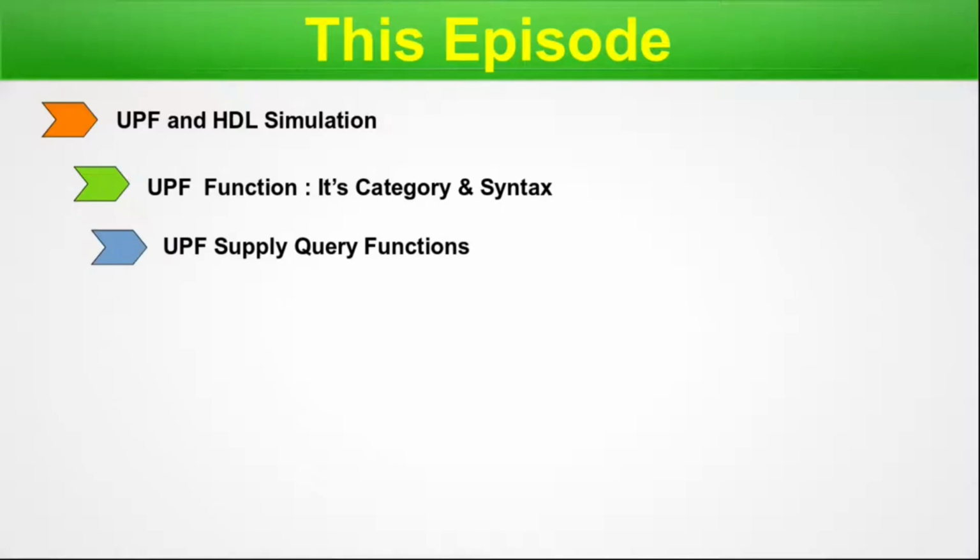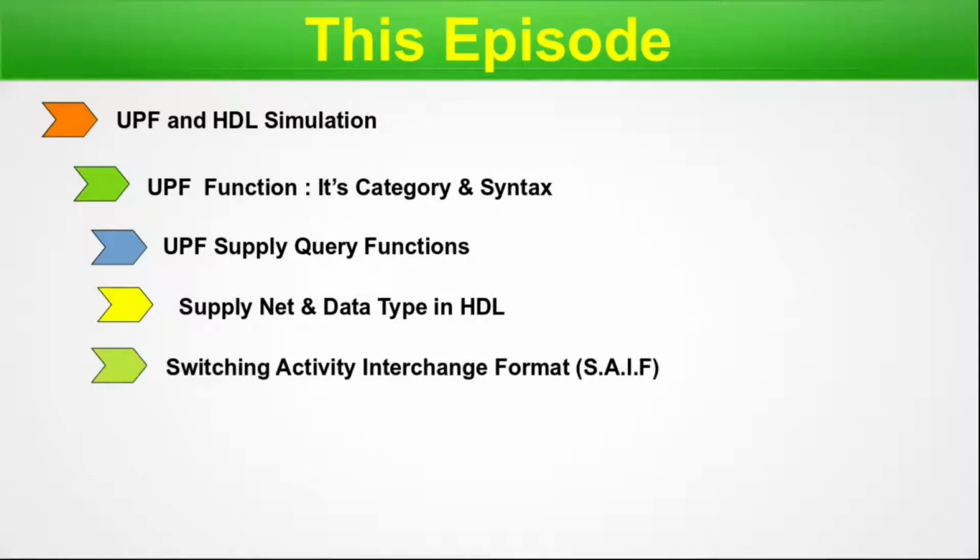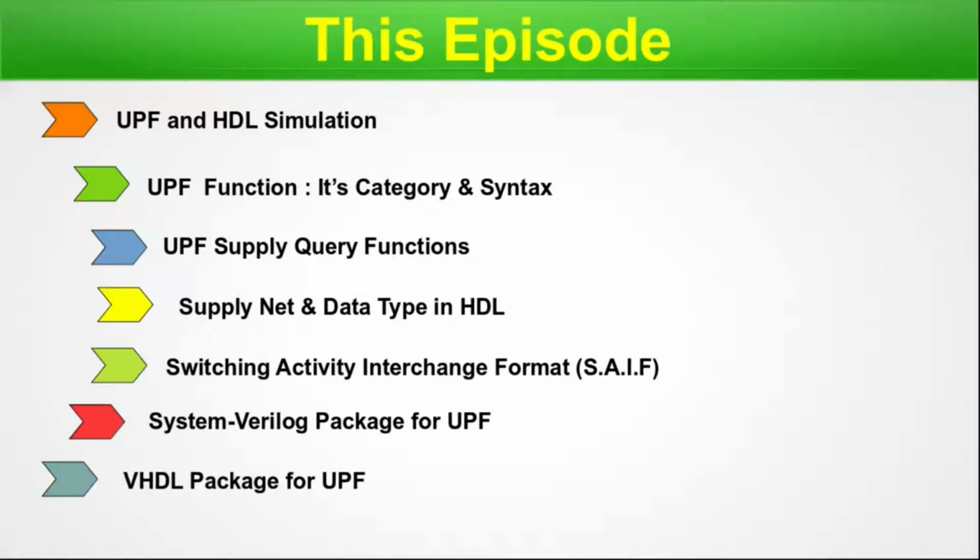Hey guys, welcome to the fourth episode of Unified Power Format. In this episode, we are going to discuss UPF and HDL simulation, UPF functions, their categories and syntax, UPF supply query functions, supply net and data type in HDL, Switching Activity Interchange Format, abbreviated as SAIF, the SystemVerilog package for UPF, and the VHDL package for UPF. So without any further delay, let's begin.